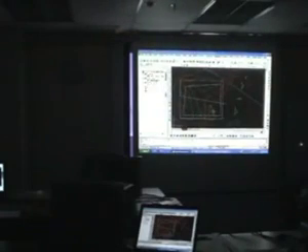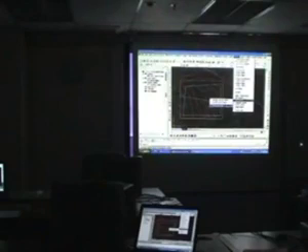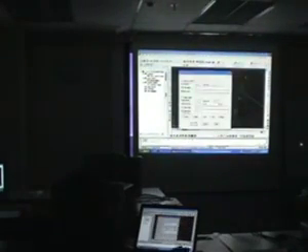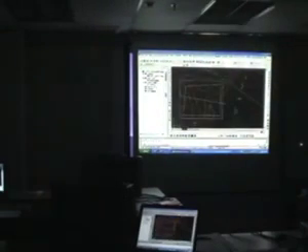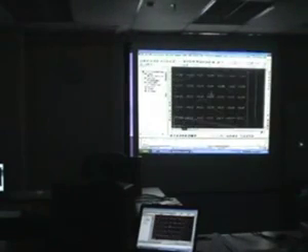Right. Let's say you need to generate any drawings based on those volume calculations, for example, you want to have grid volume ticks. Just going to go to grid volumes. There's an option here, grid volume ticks. You just click OK, and you specify what the interval is between each tick. So I'm going to use an interval of 10. Click OK. And I'm going to zoom in so you can see the values.